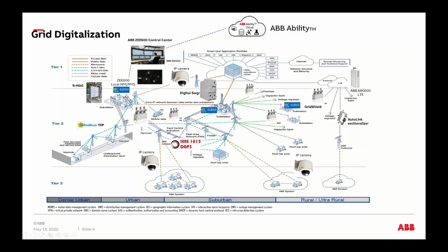So you could see here, once you're done with your substation, the job is not done, because outside the fence, outside your substation, it's a big grid where you still have to utilize all these devices. You need to upgrade them. And maybe you could still utilize other protocols. I'm showing here Modbus TCP, for example. DNP3 is still widely used in the US outside the fence, right? So you need to make sure you also comply with that protocol if it's still used on the poles.